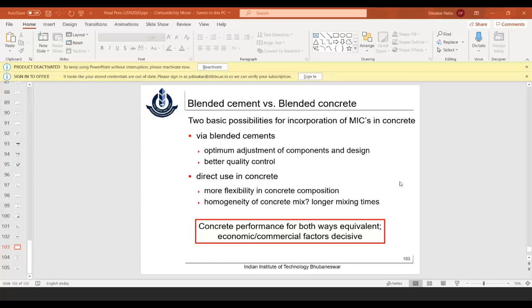Like the slabs, if you want to remove the props I showed you in the beginning, normally it is 14 days to 21 days. Do it judiciously, with all the curing processes, even with the blended cements. After that, in blended cements, definitely 60 to 70% of the strength will be achieved. In spite of removing the props, also continue curing the elements for another week or 10 days.